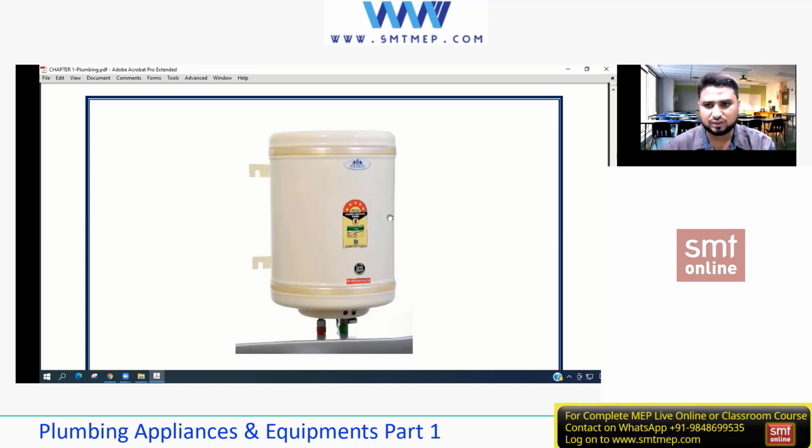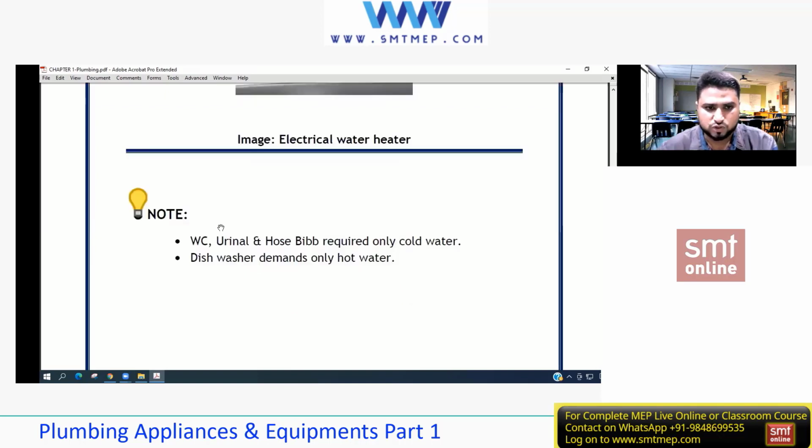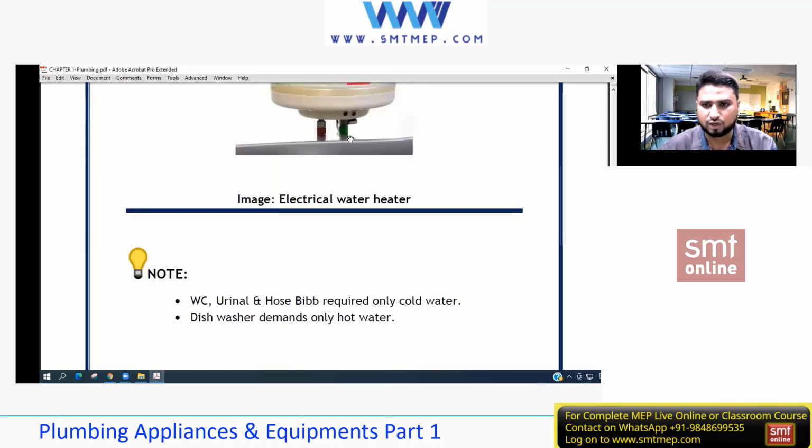So why are we learning these fixtures and appliances? Because when we are dealing with any kind of project, first of all we need to know what kind of project we are dealing with, and we need to know what amount of water or what kind of water each fixture or appliance demands, cold or hot, so that we take it into consideration and do the pipe sizing and selection. Now, this is a very important point. Note, WC, urinal and hose bib require only cold water, whereas dishwasher demands hot water, and electrical water heater also demands hot water. We can include this.